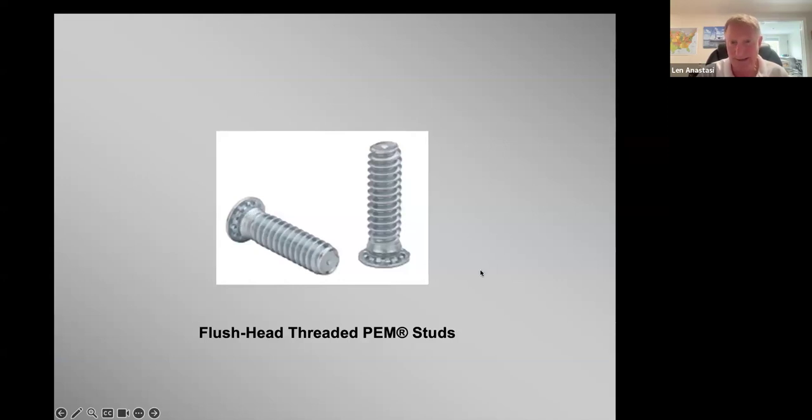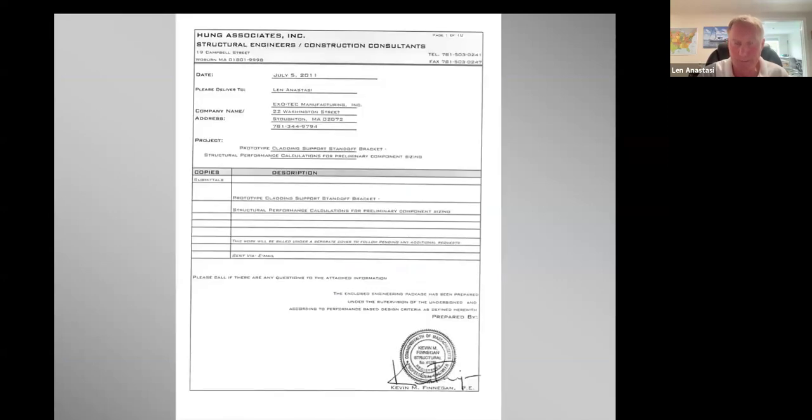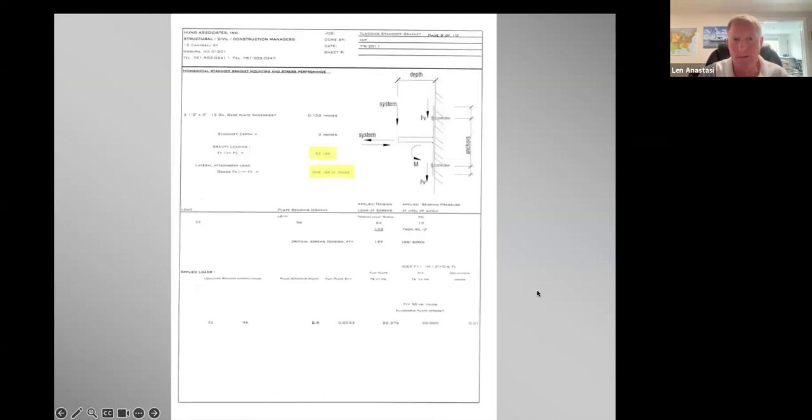In all reality, I didn't think it was going to work. I think when you put a compression load on, it's going to pop off, but it ended up working. So I had an engineer calc it all out and said, show me what I need. And he said you need 32-pound gravity load for compression and suction wind load. You need 266 pounds force there.